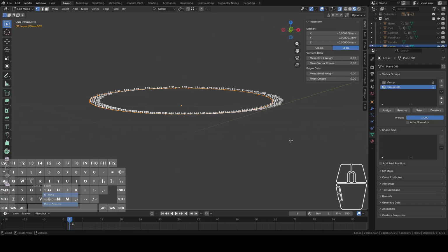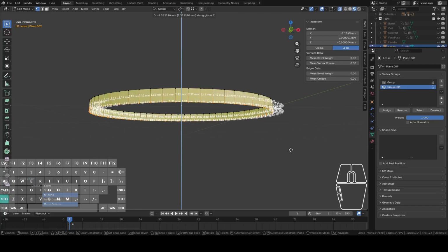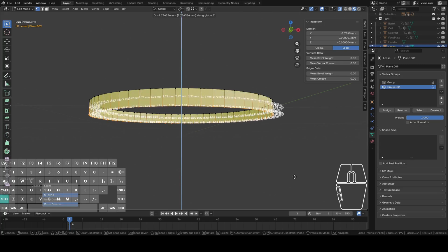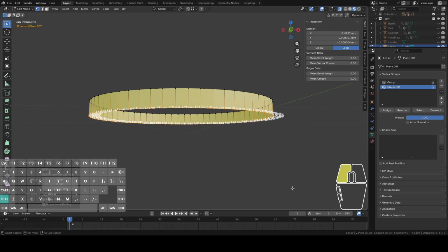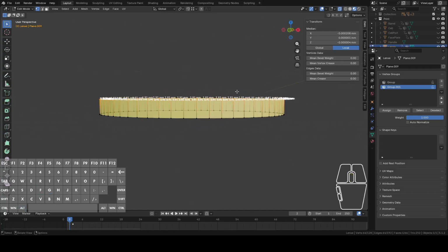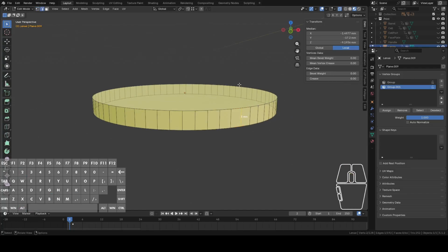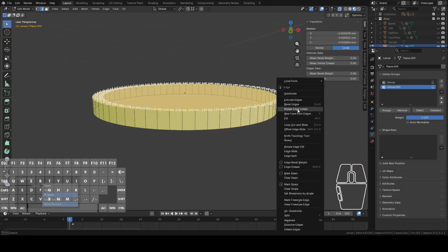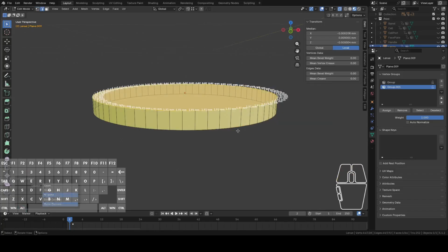And let's then extrude this lens, and let's make it maybe 3 millimeters. Should be plenty. And then we'll hit F to get a face in there, and then hit F on the top as well. And then let's bevel this. Should we bevel both sides?